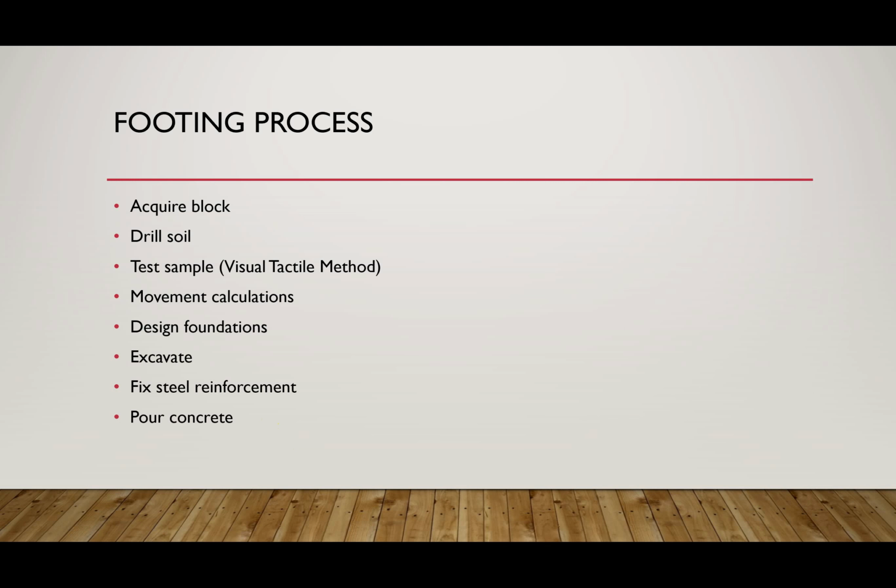We have to go through and do some calculations about the movement, so how much the ground's going to move, and then we design our foundations around it. After we've done the design, our trades will go out and excavate the ground. After they've excavated the ground, they'll lay a couple of tarp things on there, which we'll go through shortly. They put a bit of steel in the ground, and then they pour the concrete over it. So it's not a very big strenuous activity that they go through. It's pretty systematic.